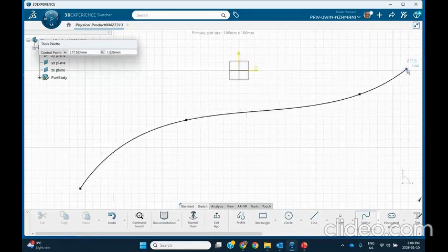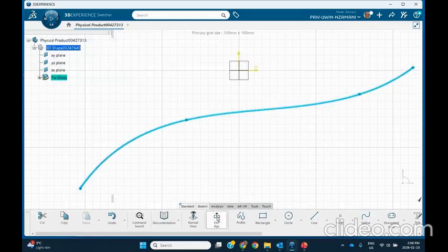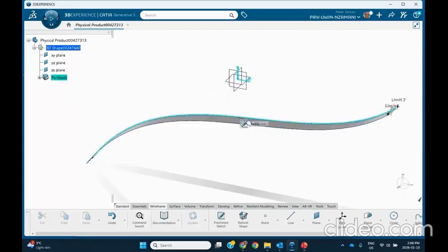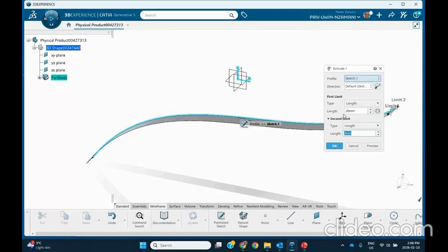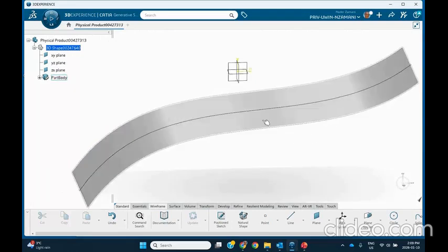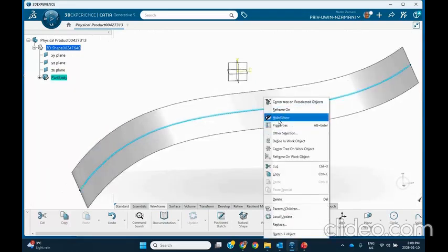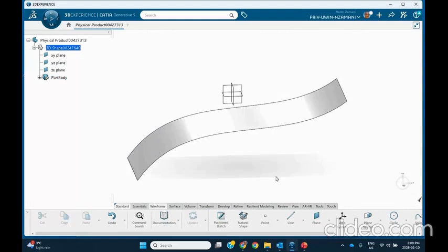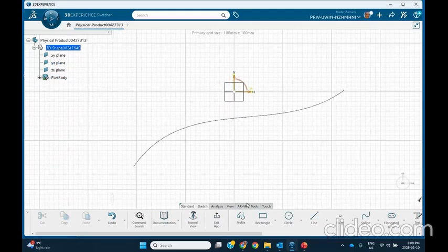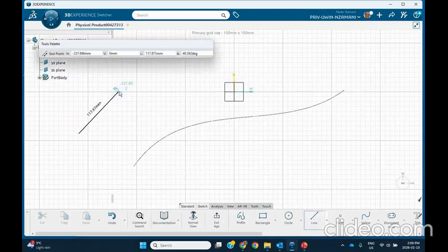So I want to extrude it to get a surface. Okay. All right, so let me see. Extrude it by 100 and mirror extend so that we have a bigger area right there. I'm going to hide that sketch. Now I'm going to make a direction. So on that vertical plane, I will sketch a direction, something like that.